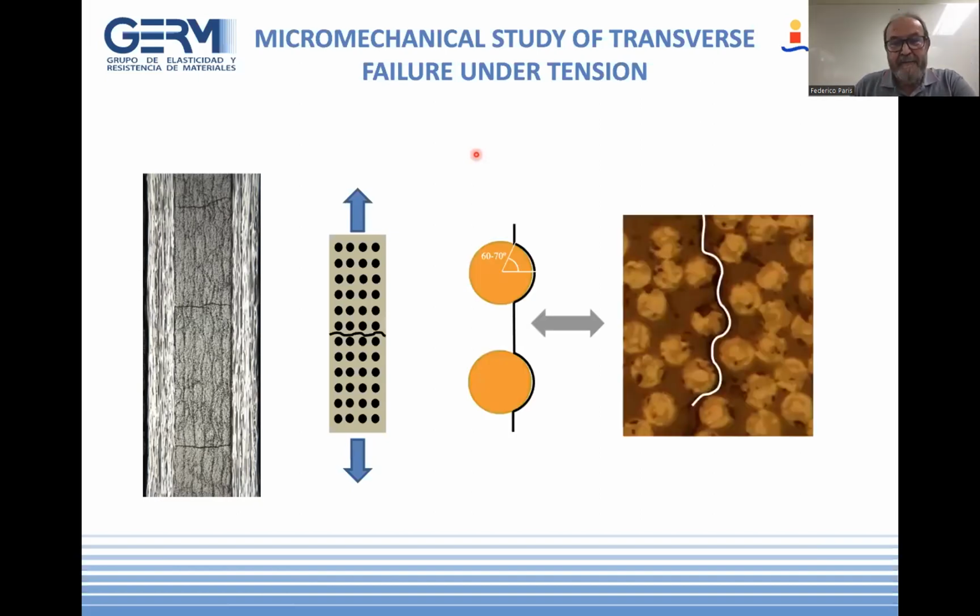And then the micromechanical analysis of this problem predicts that a debonding crack will stop at the angle of maximum hoop stress. Is this corresponding to a direction normal to the applied load? This fact can be observed on the right hand side.